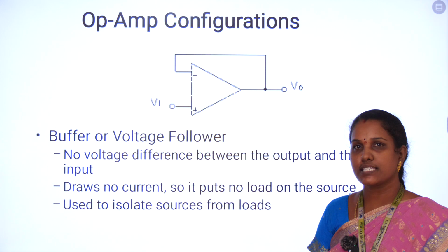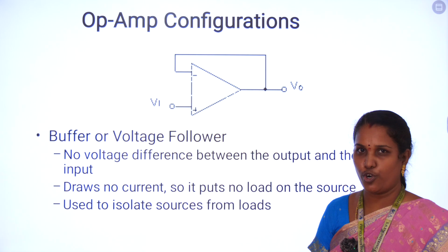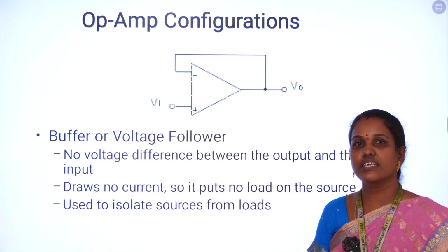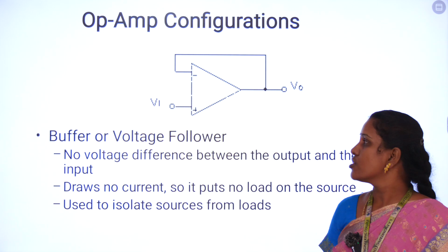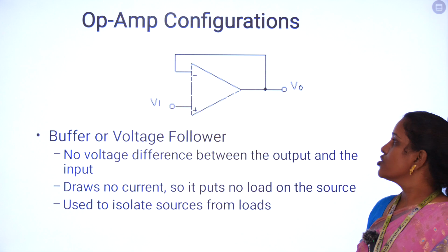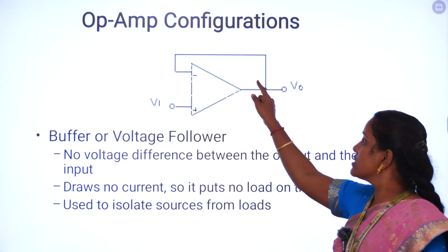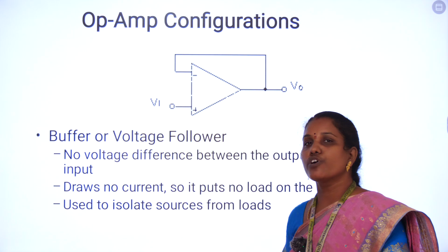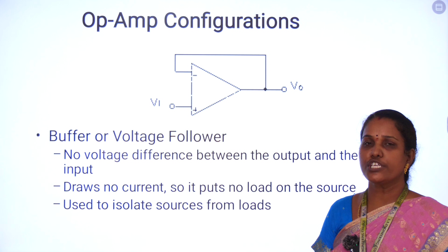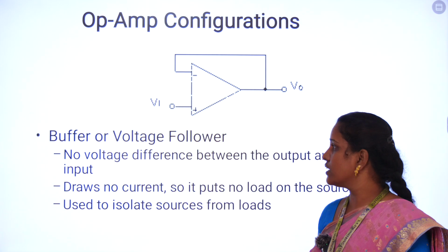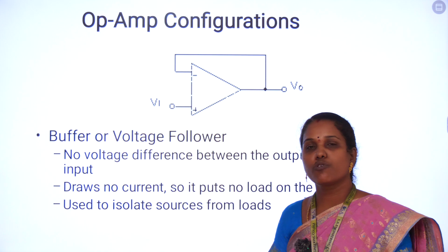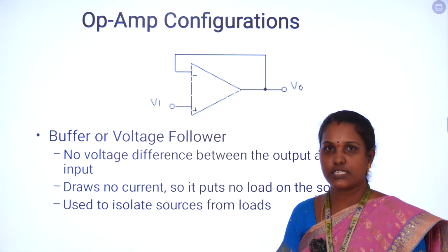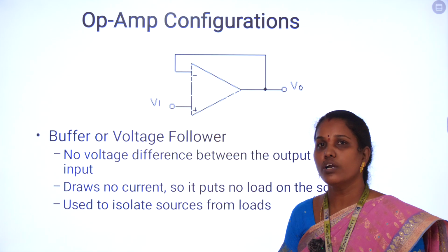For this kind of IC741, we can use it as a voltage follower. A voltage follower is nothing but the output voltage being equal to the input. That means the gain of this circuit is equal to 1. So when the gain of this circuit is 1, you can give a feedback signal. This feedback output is given to the inverting input terminal. With this diagram, we can use it as a voltage follower. These applications can be used for a buffer also. A buffer is one of the digital circuit components; you can store 1 bit of data because it is nothing but output equal to input.